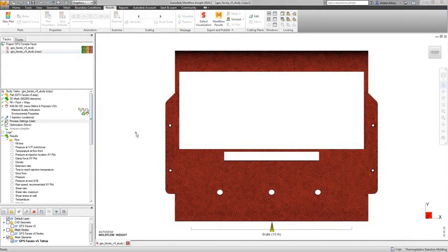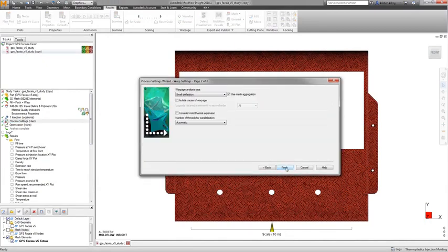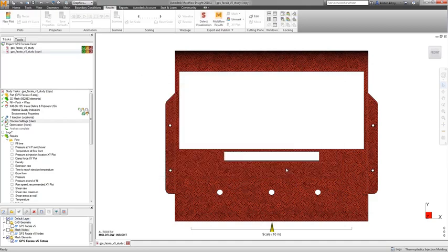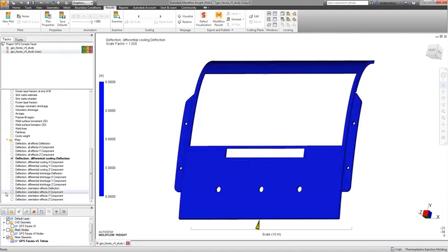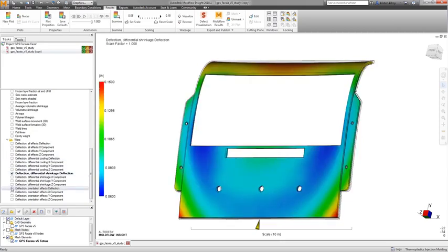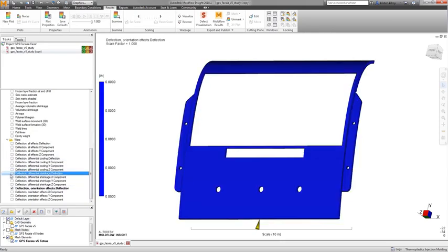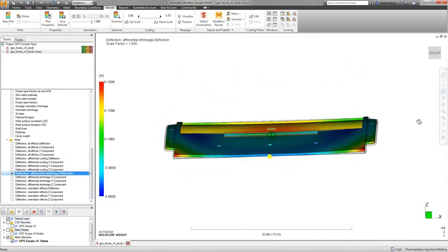If troubleshooting the deflection of your part, enable the option for running the warp analysis with the Isolate Cause of Warpage option, enabled within the process settings. This creates additional result plots that help paint a clearer picture to identify if warpage is due to one or all of the three major causes: differential cooling, differential shrinkage, and orientation effects. Back to the GPS plate, the main cause for deflection is differential shrinkage.